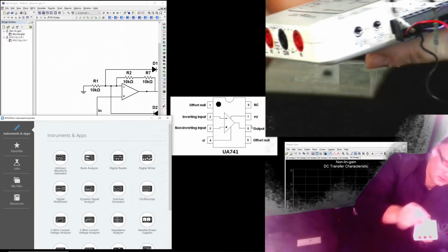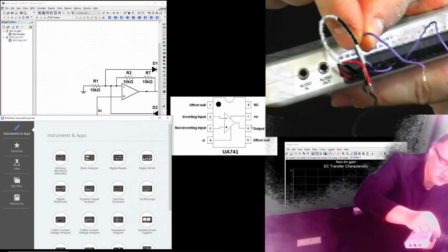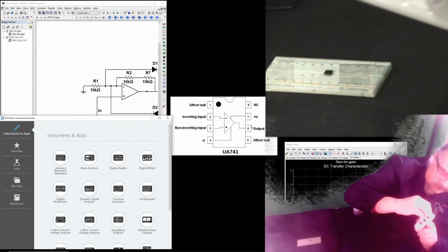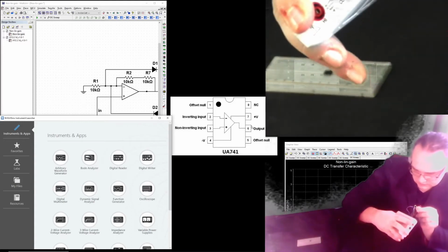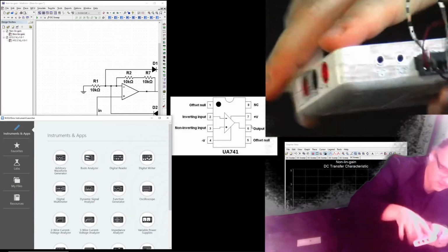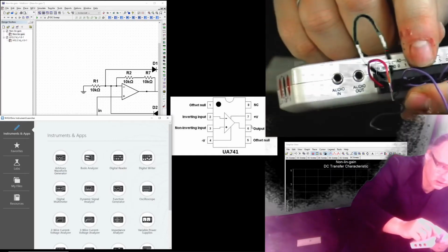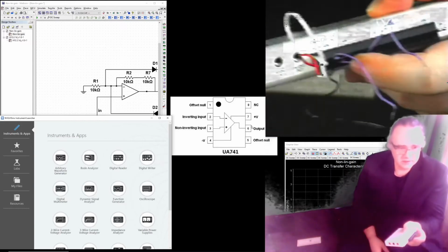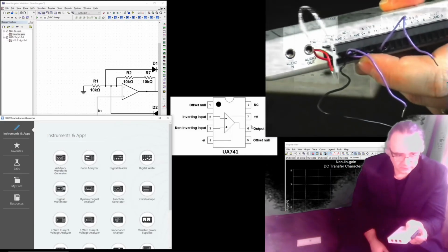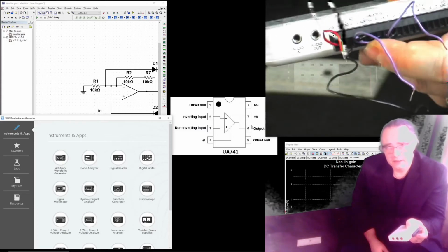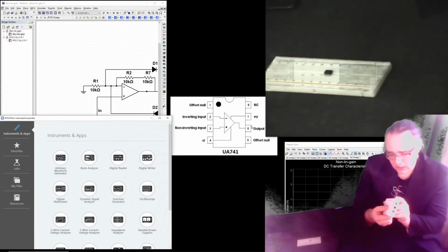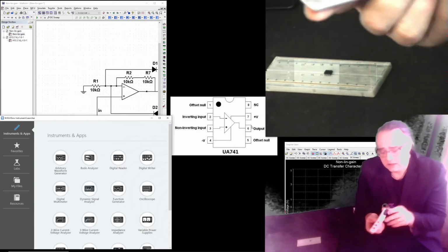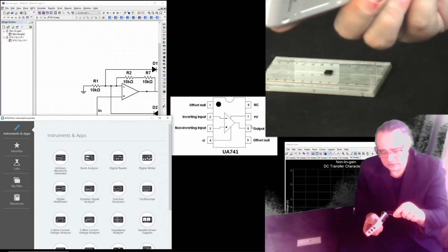Then I connect the signal source, which is, in my case, analog output 0. I connect it locally to the analog input 0 plus, which means that when I monitor the inputs of the MyDAQ, the analog input 0 plus will always give me the signal that I generate from the signal source.